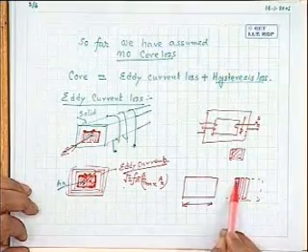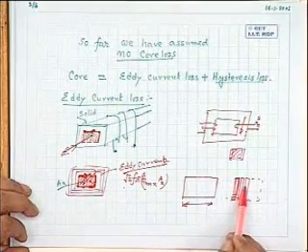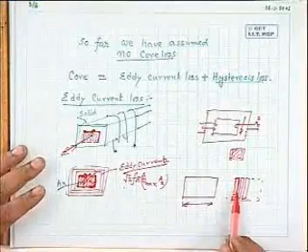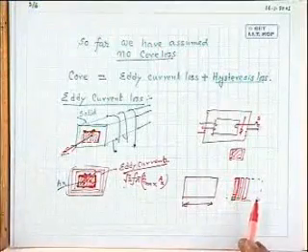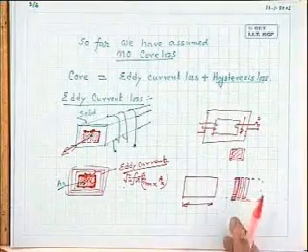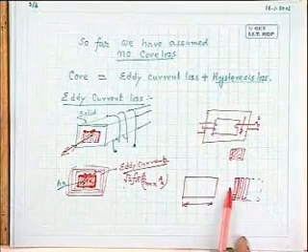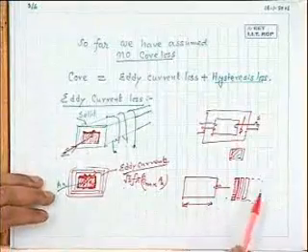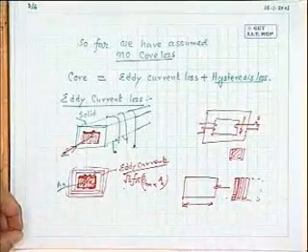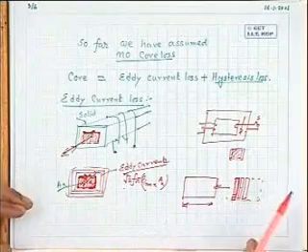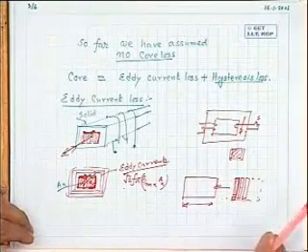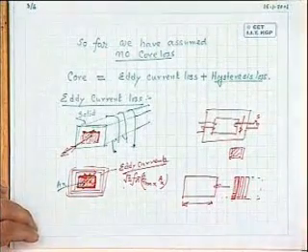However, one point should be very clearly understood. Whenever you talk about many plates stacking together, each plate should be electrically insulated from the other. The moment they are not electrically insulated, it is the same as this one, because the current will then flow once again over the whole area.